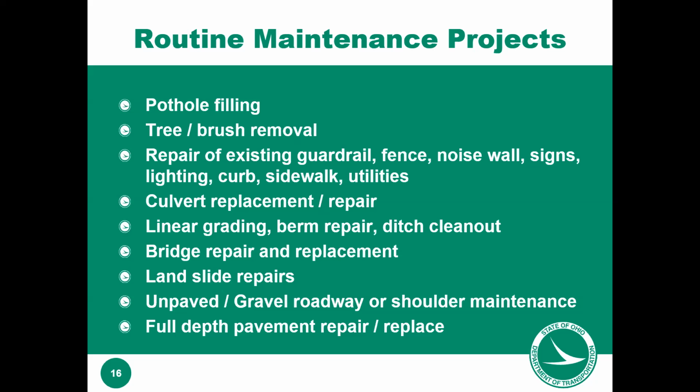So this has a lot of potential application in your highly developed roadway projects. So in the middle of a city, you might have a big roadway project that goes a few blocks that is sidewalk to curb to pavement to curb to sidewalk. And so you could do full depth pavement repair there, and from an Ohio EPA standpoint, not need construction general permit coverage and not need post-construction BMPs. You might have some local requirements, but there's a lot going on there.